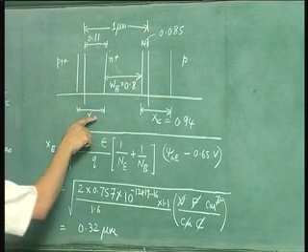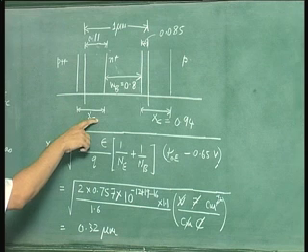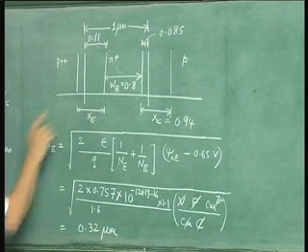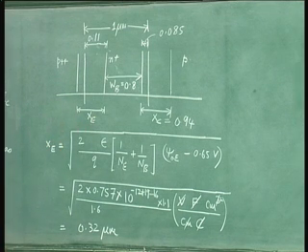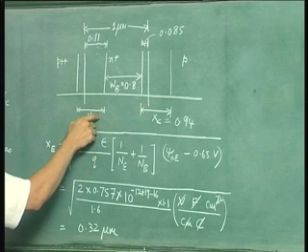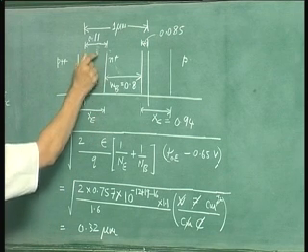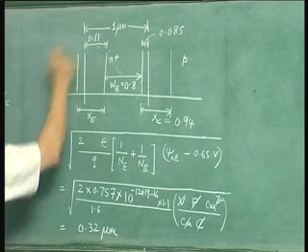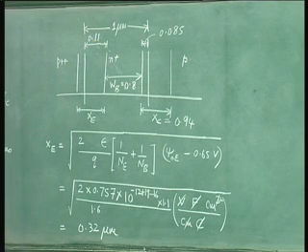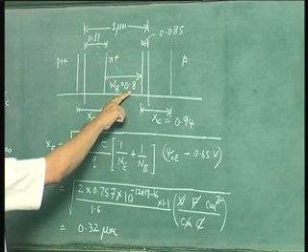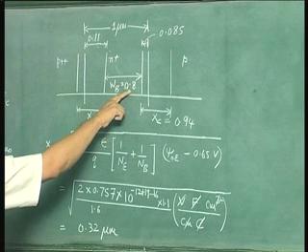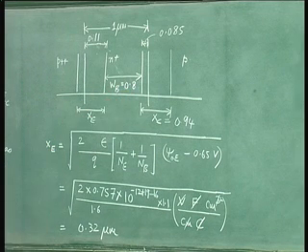I leave it to you to calculate the value of XE for a forward bias of 0.65 volts. Ultimately you will find that this XE will result in the depletion layer on the base side of 0.11 at 0.65 volt forward bias. So this is the base width which we must use in our estimation of alpha.